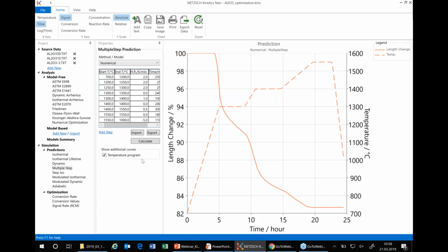If the heating is too fast, the heating rate is too high, then the shrinkage could also be too intensive. And if we have some temperature gradient, then different parts of our material could have completely different shrinkage values, and therefore we have some mechanical stresses, and we can have some micro cracks inside the material, and we lose quality.